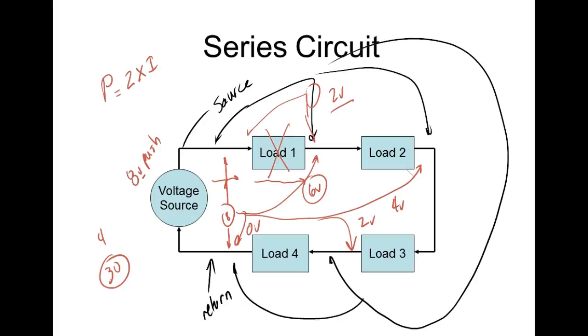It allows us to use loads that are rated at a lower voltage, but if one of them goes out, that means they all do what? They all go out. That makes sense? So we do this a lot. Christmas lights, a perfect example. Christmas lights are what we call a series parallel circuit. They used to be series, and if you lost one bulb, they all went out, and then how do you troubleshoot them? Get a good bulb and do what? Move them down the line until you figure out which one. Of course, there is an easier way, with one of those voltage detectors.